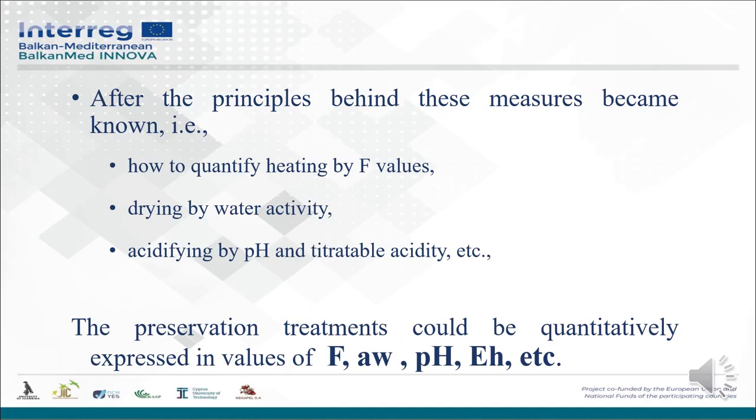After the principles behind these measures became known, for example how to quantify heating by F values, how to quantify drying by water activity, how to use acidifying by pH and titratable acidity, preservation treatments could be quantitatively expressed in values of temperature, water activity, pH, etc.